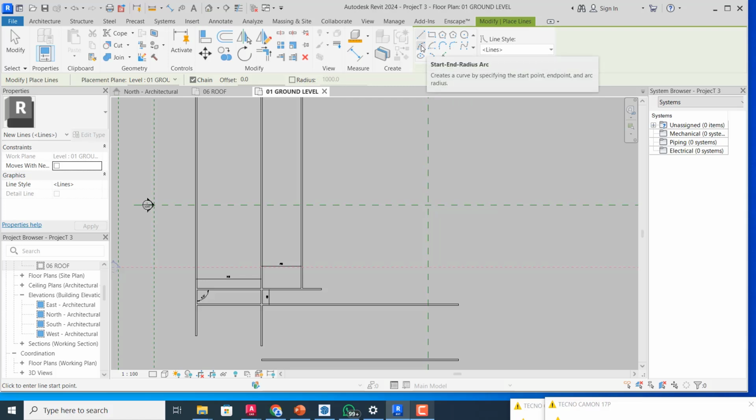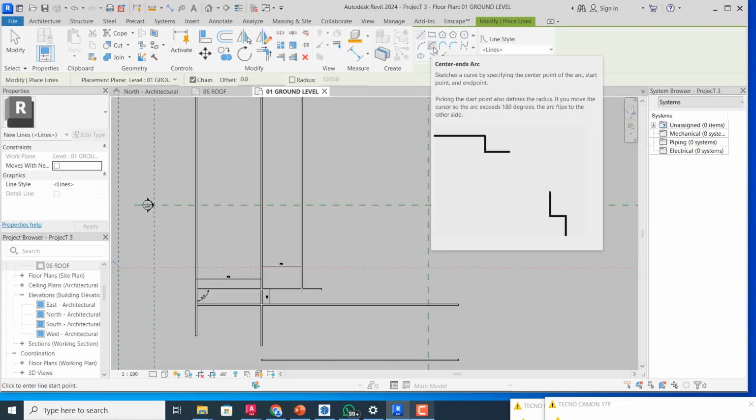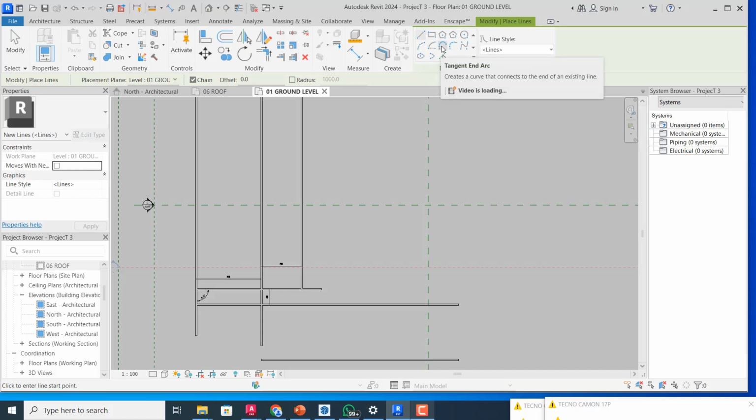You can see there are points showing in the preview, the first, second, and then the radius. Similarly, this is a 2-point arc. All you need to do is to specify the center and then the ends. We have tangents, fillets, arc. So we may not go deep into all of them, but we'll briefly explain some of the key important tools here that you will be using in most of your jobs.